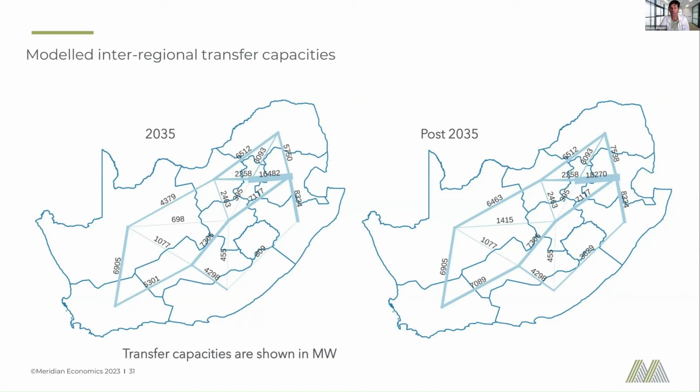But for long-term storage, such as monthly or interseasonal, batteries aren't efficient, and pump storage is far better. Now, pump storage's round-trip efficiency is less than batteries, so that's a downside. And because you can't choose where you put your pump storage, it's less suitable for ancillary services. Now, on your comment that with pump storage you need a bigger amount of kilowatts to pump up to the top reservoir, true, I agree with that.